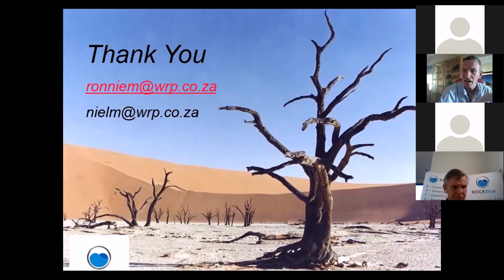So there's a guideline on that, and then you add those two together, and that gives you your expected minimum night flow. You then compare it to your measured minimum night flow, and if the two numbers are reasonably close together, then you know that you don't have a major burst problem. If the two numbers are quite far apart, that gives you an indication that you do have a burst problem in that zone.